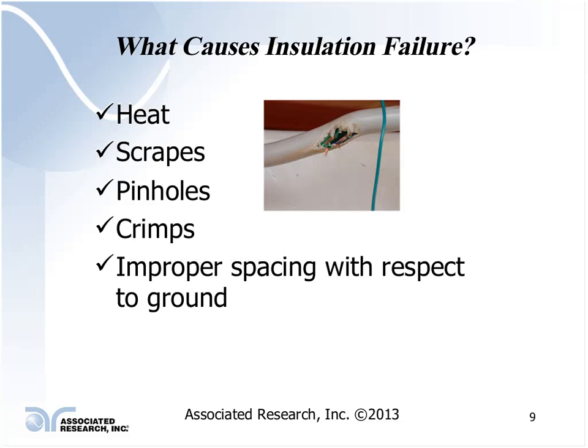I've seen this in some motor applications where you might have a magnet wire in the motor itself, where it may be contacting part of the motor, and in shipping the thing across country, the vibration damaged that varnish insulation.